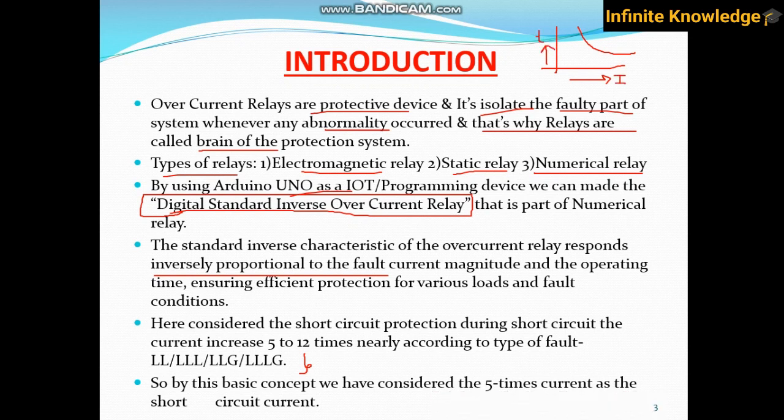So you can see at the y-axis the time and at the x-axis the current. As your current is high, your time is very low. And also it depends on the fault current magnitude. Whenever your current is high, your time is low, and the operating time ensures efficient protection of the loads against the fault condition. Here we have considered overcurrent as well as short circuit relay.